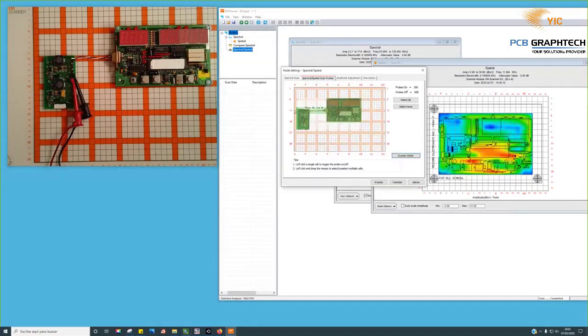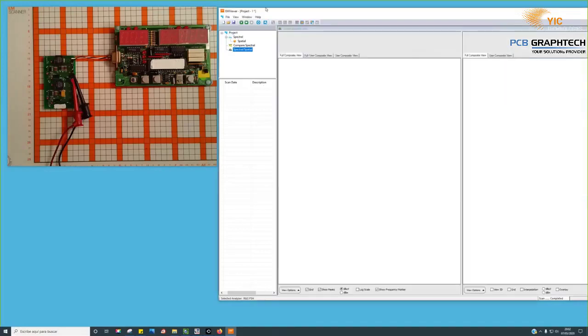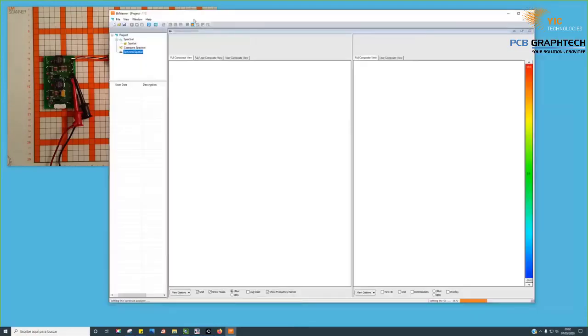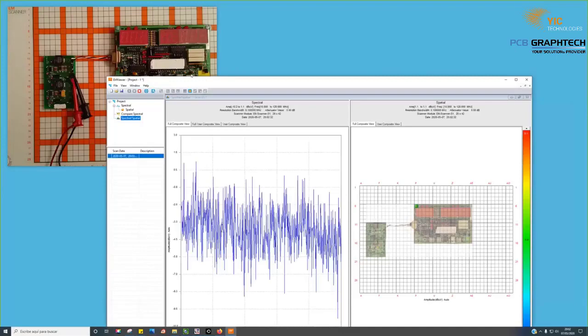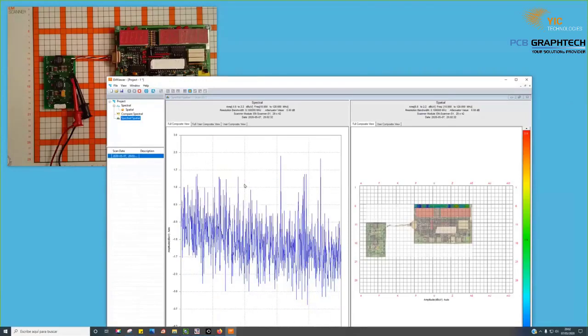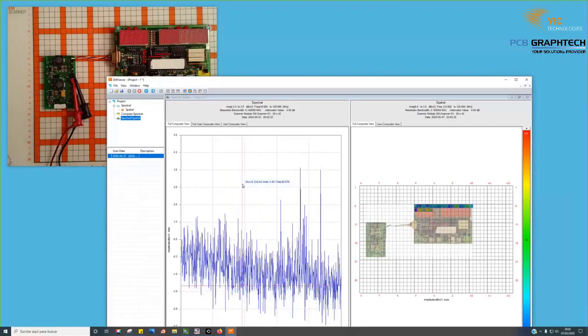And then here I need to remove these lines here and select. Not necessary really, but in this way perhaps we will have a faster scan. So I have here the picture, accept, and then I can run the analysis. So now the system will be scanning for the full number of cells in the full frequency range. In this case, from 10 megahertz to 120 megahertz with a 125 kilohertz bandwidth.